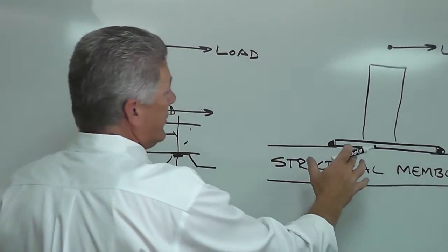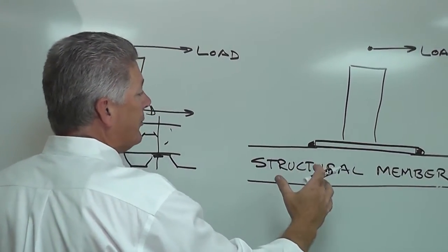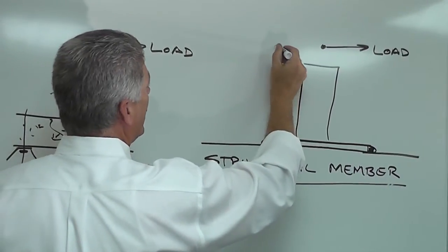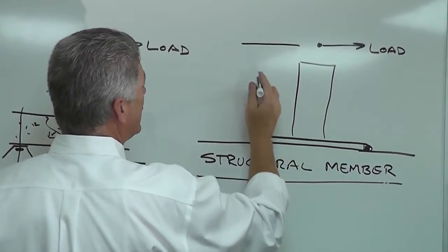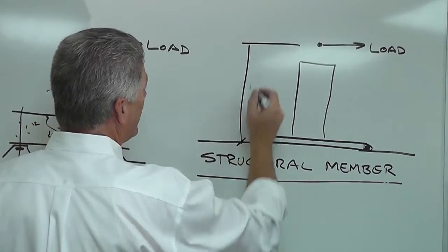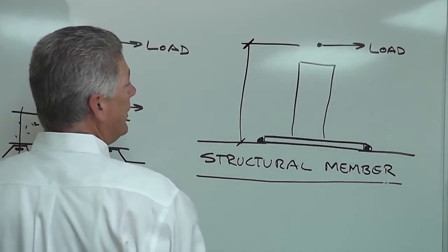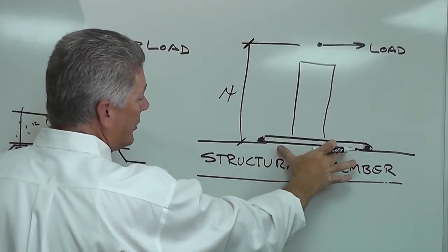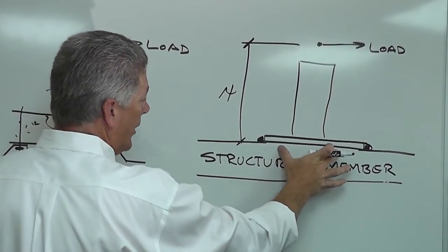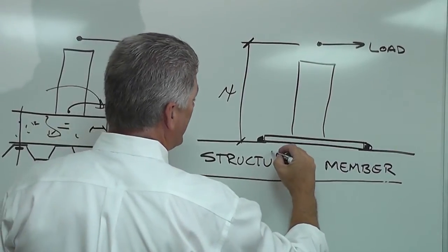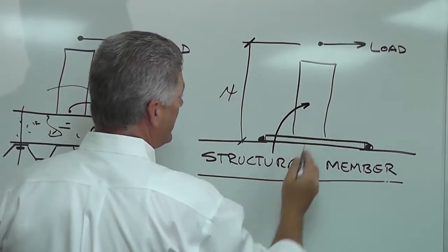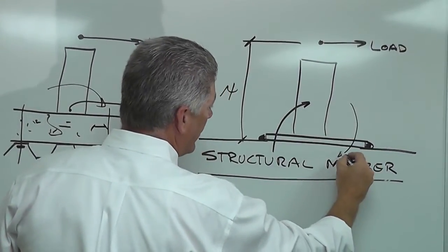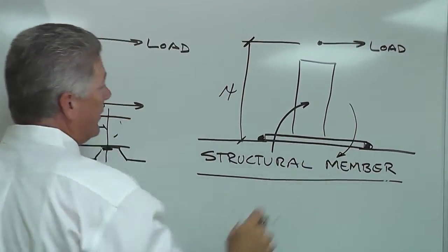In a rigid post design, the opposite happens. There is no tip-over technology to it. It's all rigid. So now what ends up happening, depending on the distance from the connection point to where the load is being applied, adds to the amplification of load at the connection point. So you end up with a situation where you have rotation about the base in this orientation, creating tear out, and then you also have another load orientation creating compression down into the member.